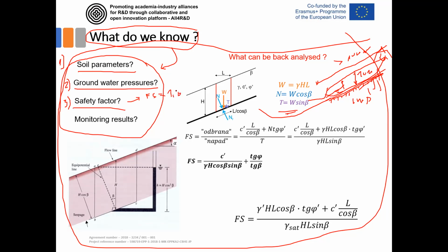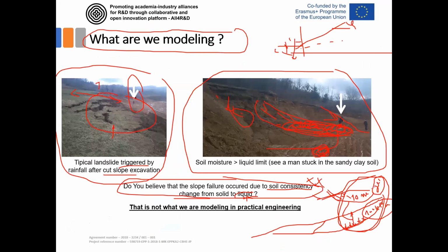If we get to the site, to the field, and we see that sliding occurred like we see here, we definitely know that the sliding occurred. Large displacement occurred. There are typical cracks at the top. There is this typical bulge at the bottom, on the landslide toe. So the sliding occurred. What we can be sure about this landslide is that its safety factor is equal to 1.